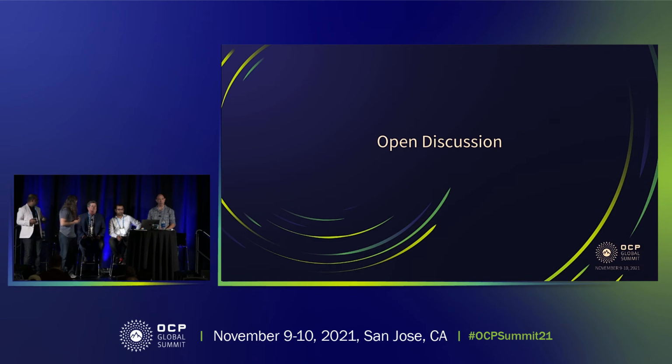So the part of this where you're creating a standard interface and identity seems well-defined. How strong of a statement do you want to be making on out-of-band recovery? Some examples I could think of: one, you could say you should rely on a BMC to be able to update BIOSes. Or you could make a stronger statement that the external root of trust managing that flash should be able to force an update. How strong of a statement do you think you're going to have as part of this activity?